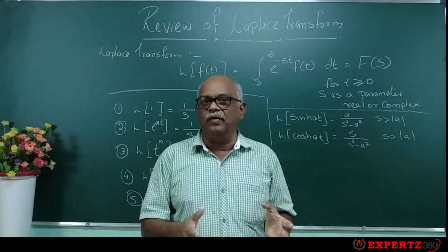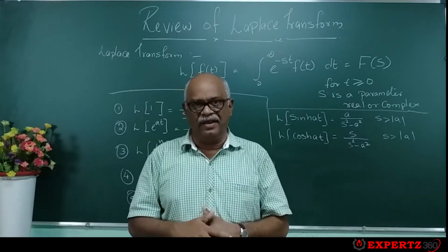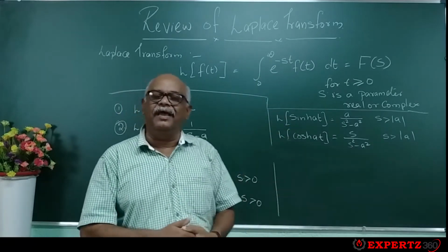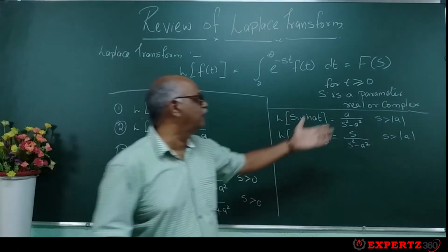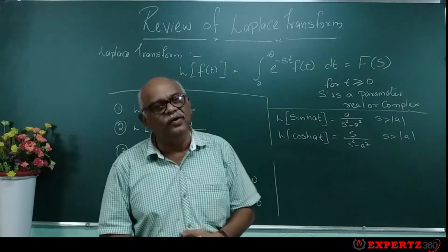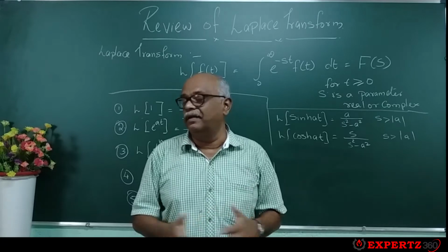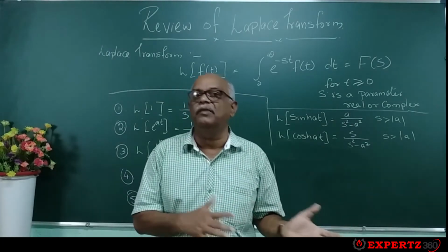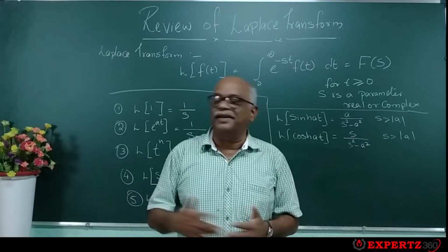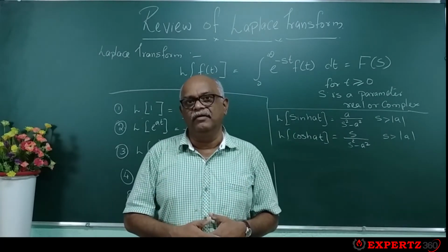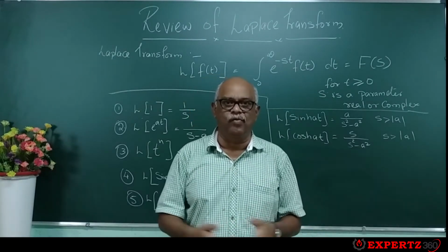This continuous time domain function, I will put into the S domain, that is the Laplace transform, then put S is equal to j omega, and it goes into the frequency domain. So j omega is a complex value. Okay, put S is equal to j omega. Then if it is not continuous, if you have discrete systems, then you will go for the Z transform instead of the Laplace transform, and you will be putting Z is equal to e raised to j omega, which will go into the frequency domain. Okay, then when you study digital signal processing, you will be studying all those transforms.